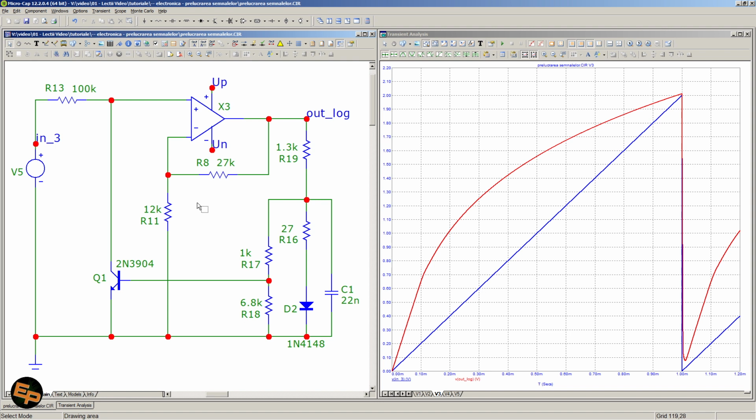We can accomplish this by having an amplifier with an amplification factor that changes based on the input voltage, so that the higher the input voltage is, the lower the amplification factor will get, and the lower the input voltage gets, the higher the amplification factor we will have.